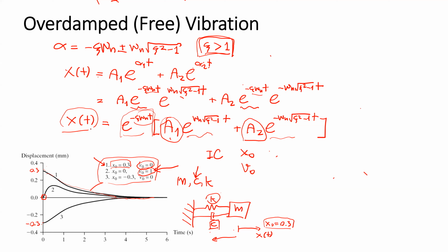So when the slope is positive, the velocity is to the right-hand side. The force from the damper is to resist the motion, so it will go downward or to the left-hand side. But when the spring pulls the block to the left-hand side with the velocity to the left-hand side, the damper resists the motion, so the force will be to the right-hand side.